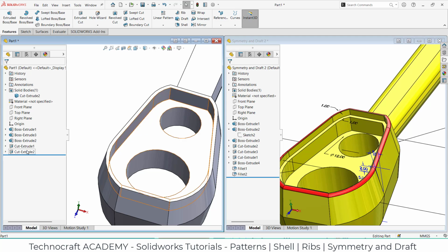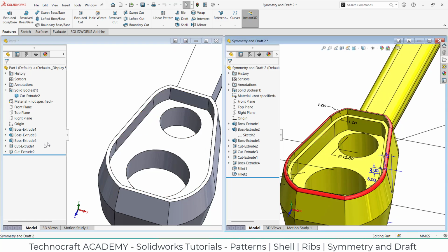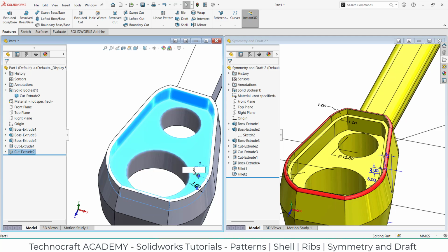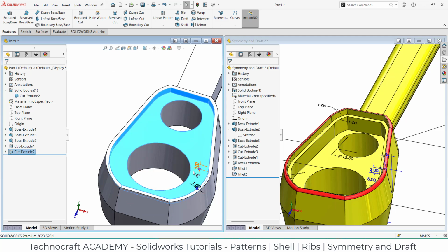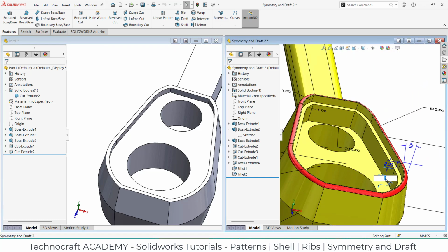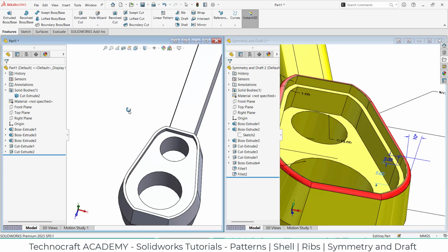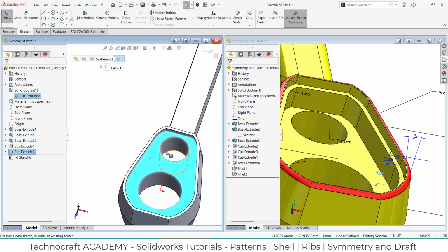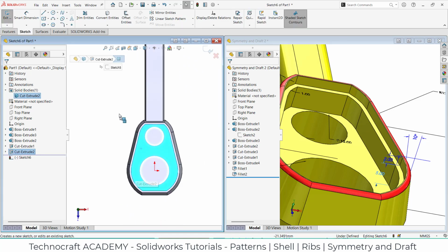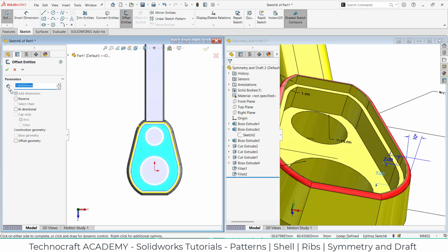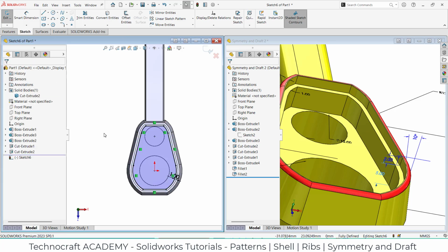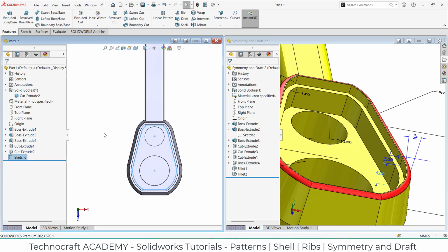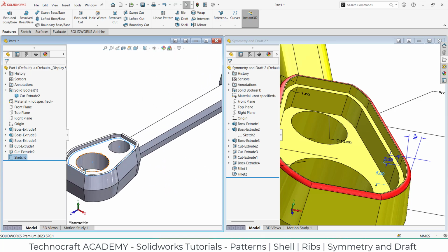Okay, let us do one thing. So I should make it 2 first, and then it should be 5 from this face. Okay, now again I need to select this face, sketch on this, make it normal, just again offset it inwards, green check, exit the workbench, make it again isometric view.